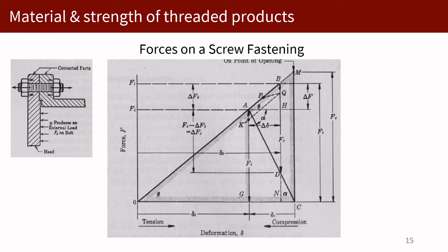using your torque, with the torque wrench in your tightening, you reach this point, point A. So at point A, that is your initial tightening force. Okay? So now let's look at the x-axis. The total you reach on the x-axis is the total elongation or deformation of your bolt when reaching the initial tightening force.